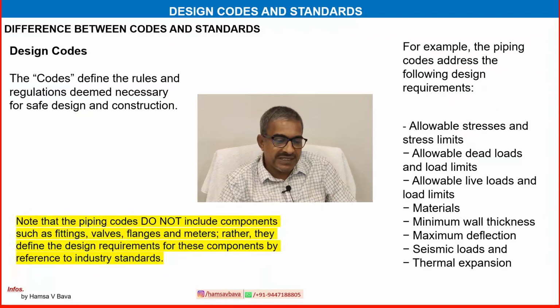One important piece of information is to note that the piping codes do not include components such as fittings, valves, flanges and meters. Rather, they define the design requirements for these components by reference to industry standards.